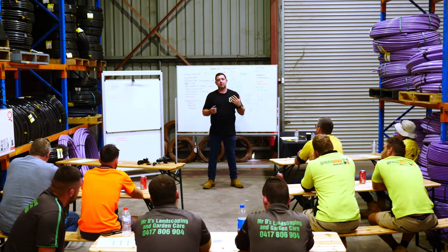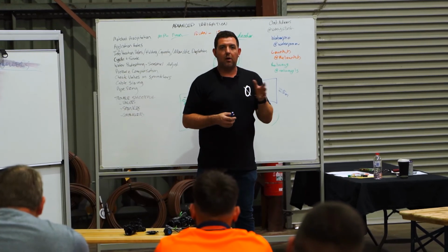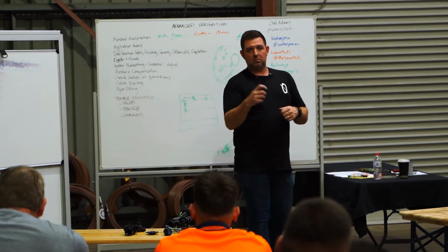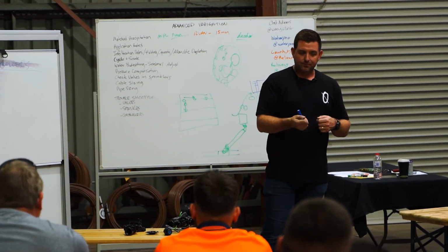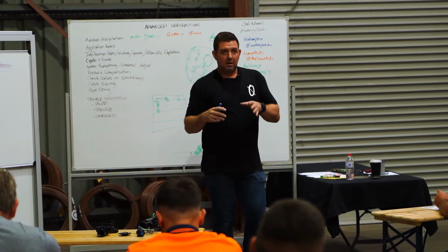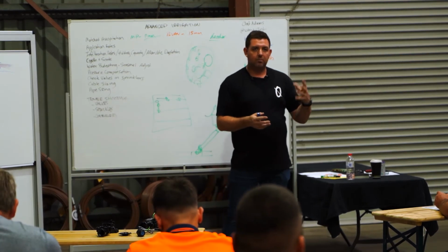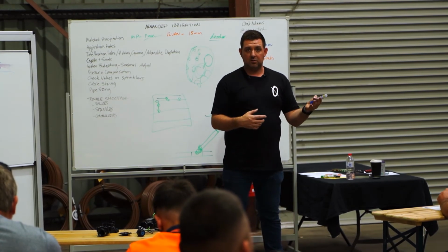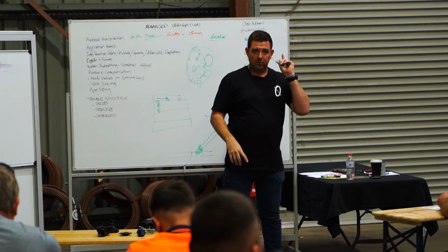For me, I always had a system of wiring of alphabetical order cable. You obviously want to make sure that you've got a nice wire stripper to make sure your wires are clean, and that you have obviously enough cables to do the valves. And I think I'm answering your question. If I'm not, tell me. When I used to install, obviously you've got an 8-station controller, you need 9-core cable for an 8-station controller because you need a cable for each of your actives and one for your common.